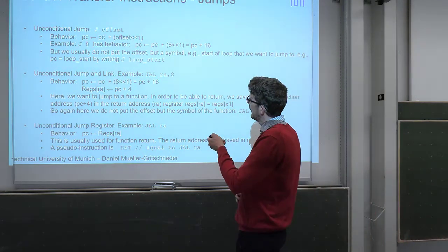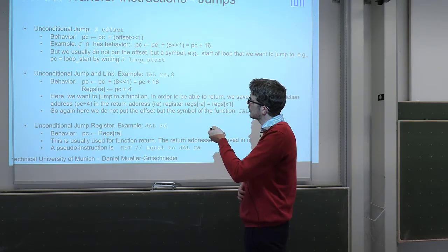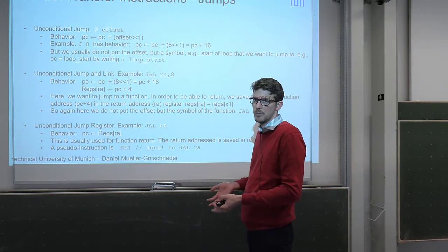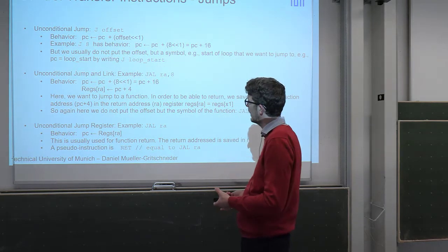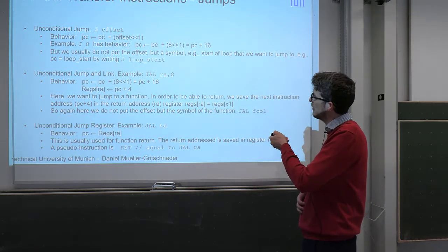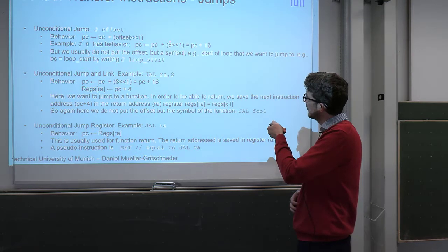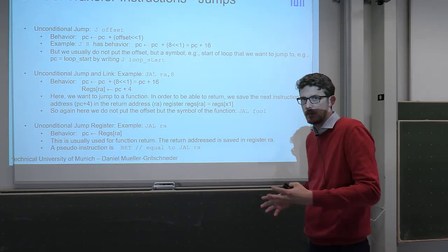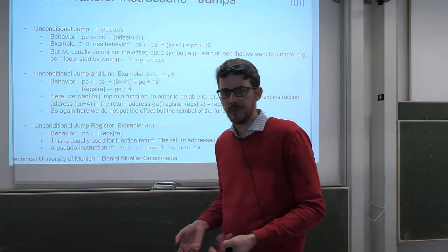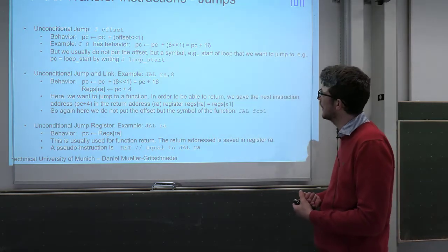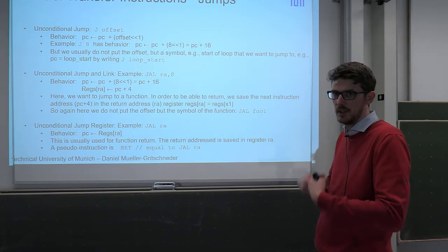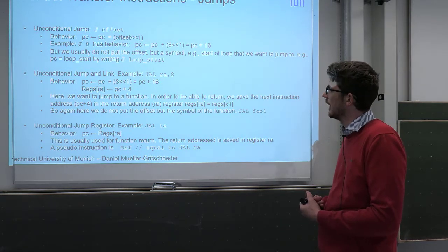So if you specify J8, which means you should jump 8 ahead, which would mean you're jumping over the next instruction, right? This is what you would first indicate, but actually if you look into it, this 8 also gets shifted by 1, so it gets multiplied by 2, so you basically have PC plus 16, so we are jumping over 3 instructions to the 4th instruction, right? So the next 3 instructions would not execute because the PC just jumps over them.